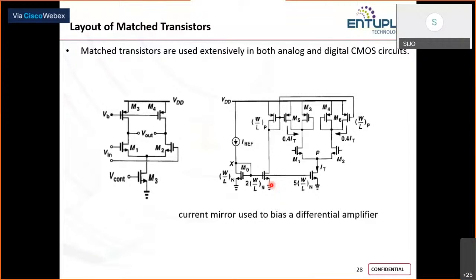So what is possible will depend upon your application, whether it's high speed, PMICs, or an RF circuit. Depending upon the application, we may have to sacrifice something. If you are given a differential pair circuit like this and asked which are the critical ones, obviously M1, M2, and the current mirror circuits here. If possible, if you can match the other devices also, that is M3 and M4, then it is always good. But the critical ones are these, so we always give preference to them, and if the other things can also be matched, obviously fine.